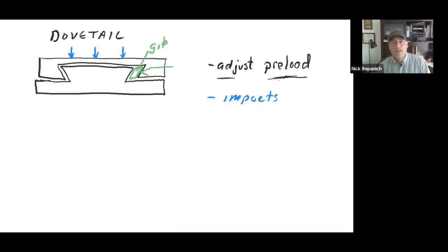pounding and impacts, but the best you can do is lubricated steel on steel, which is 0.23 or something like that. And with light loads, this moves back and forth pretty nice. I can move it back and forth with, look at this, even my pinky, right? It doesn't take much force, but as soon as you load it down, now you can barely move it. And that's just even with a few pounds, because of the coefficient of friction. So that's worthwhile talking about. This is why we are moving towards rolling elements instead of sliding elements.